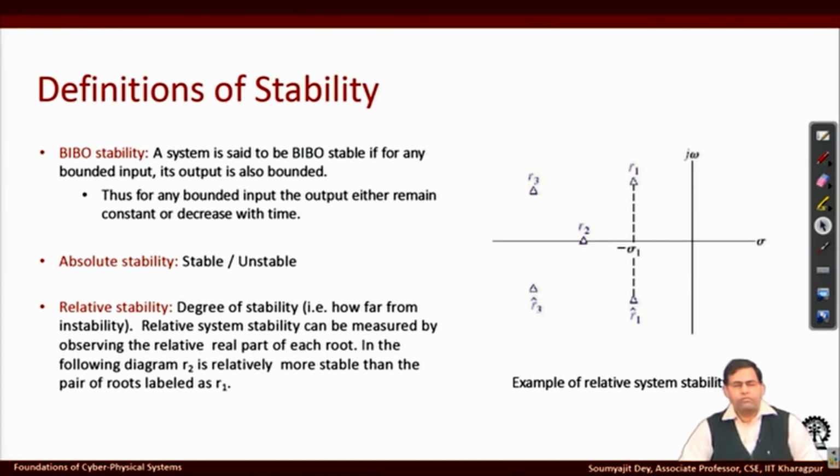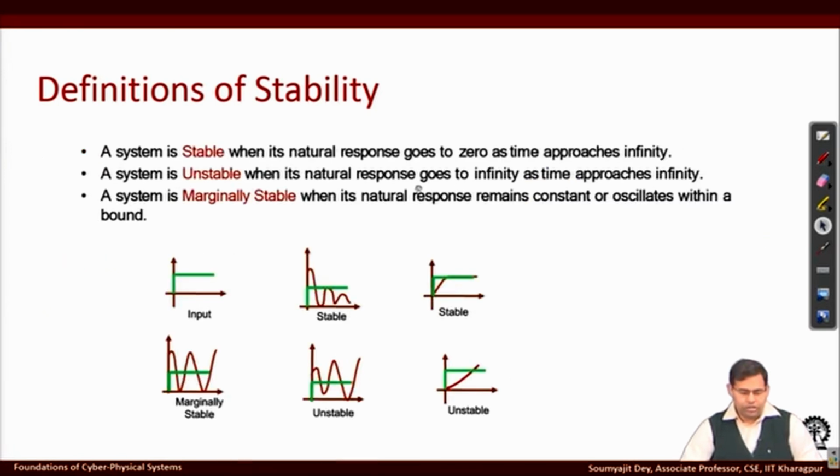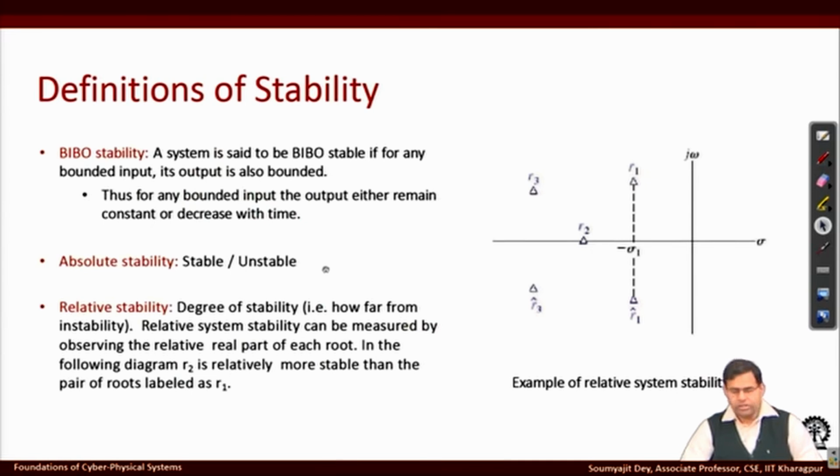If we now try to formalize a bit, we can say that a system is stable in terms of bounded input, bounded output, or BIBO stable, if for bounded input disturbance that we provide to the system, the oscillation that we observe in the output is also bounded. So that would be a bounded input, bounded output stable system. Absolute stability means this behavior. That means eventually the output response will be bounded and damped, and eventually the output will just settle around whatever is the target position.